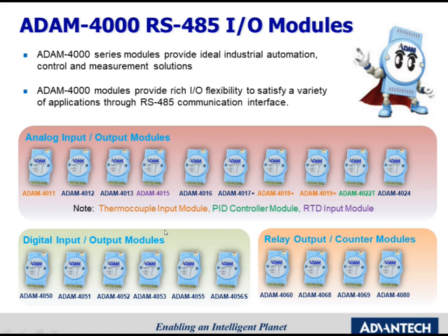In the I/O modules, we can notice that there are some modules with orange color. These are thermocouple input modules, which can be used to sense temperature. The green one is the PID controller. And the purple one is the RTD input module, which can also be used for temperature sensing.